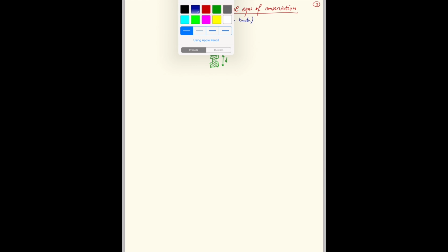It's placed in a flow, and the question is, how much drag force does the flow impose on the bar? Or put differently, what force do we have to put on the bar to keep it in place and not move with the flow? So the drag force would be my Fd, and the sign convention is that positive drag force on the bar is in the direction that the bar would accelerate. So if we think of the drag force pushing against, like the bar onto the fluid, it's minus Fd here.